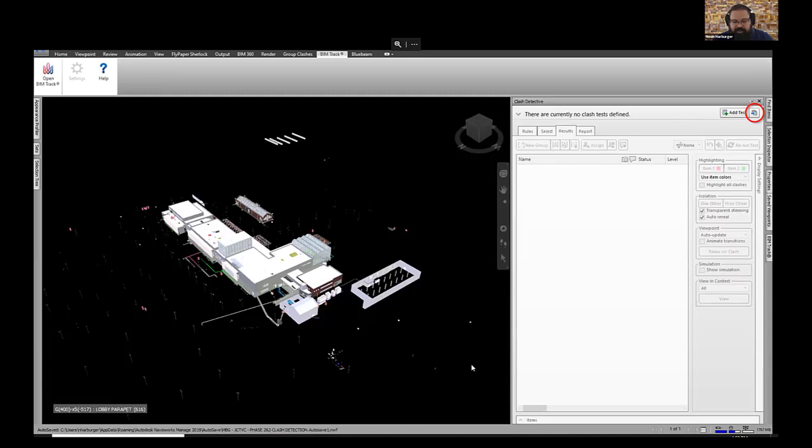And so when you take the time to set these up and save them out on any new project that's ready to do a clash detection process, from the time I start exporting those NWC files out of Revit to the time I have my report in hand of all the clashes in the project I want to look at, is maybe 30 minutes versus the half day or full day it would normally take to set all those parts up from scratch each time.